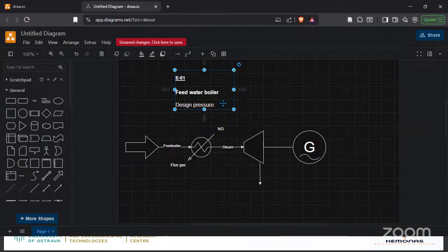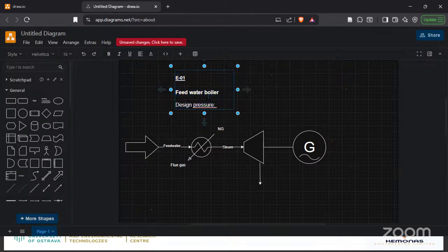Okay, and also there will be a backup generator that will supply power before the startup of the plant. So all these things need to be taken into consideration, right? So let's say we'll give it a design pressure of 30 bar because we plan to maybe expand in the future, right? And then we have a design temperature.